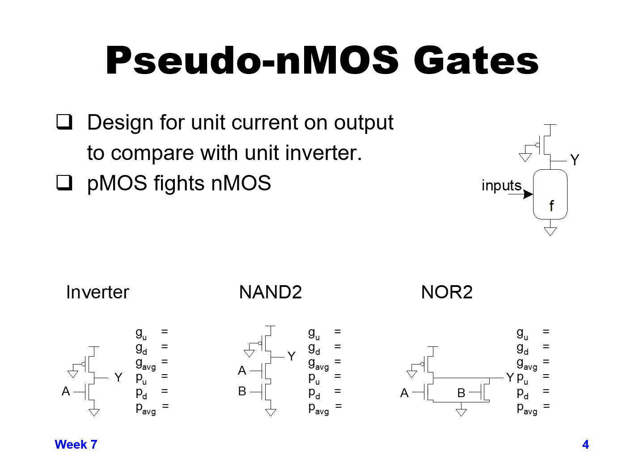So below we have the inverter, NAND, and NOR, and you can calculate the G values for the logical effort and the propagation delay values and parasitic delay for each of those. If you want to try doing that for yourself right now, you can pause and I'll present what these values are in a second.